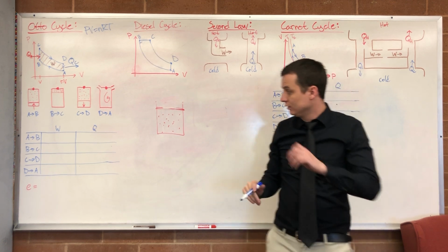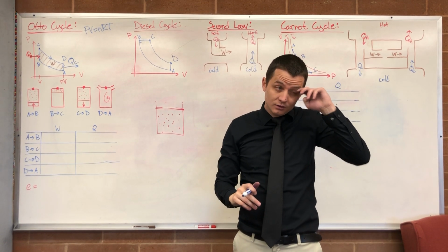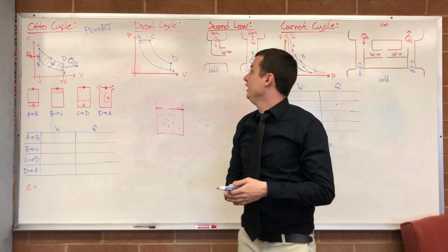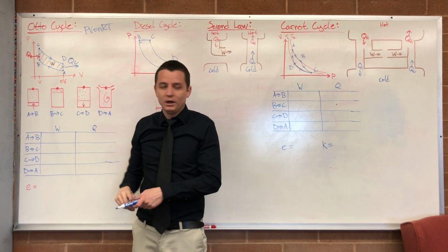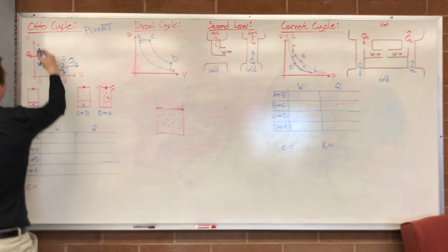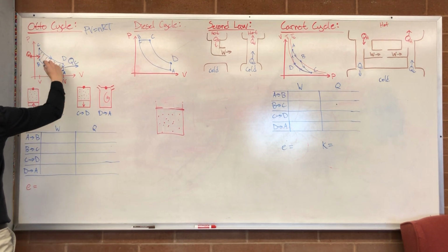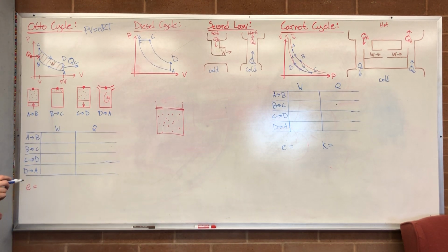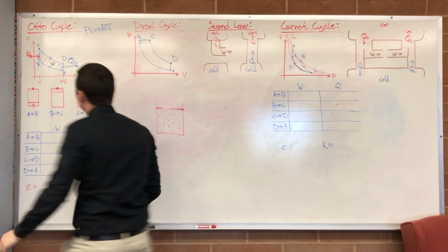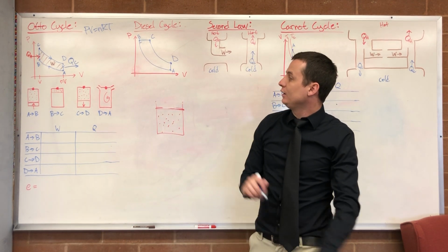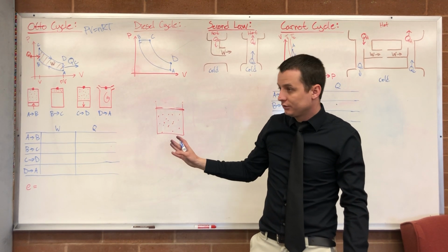So adiabatic and isothermal look the same on these guys? No. It just so happens that I curved it like a temperature line, but a temperature line might be something like running down like this, and then touch it right there finally. Okay. So, no, this isn't necessarily isothermal, but it's for sure adiabatic. No heat's being added. So from A to B, we have an adiabatic process.